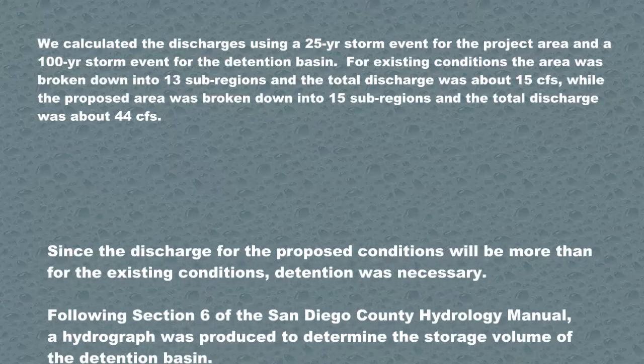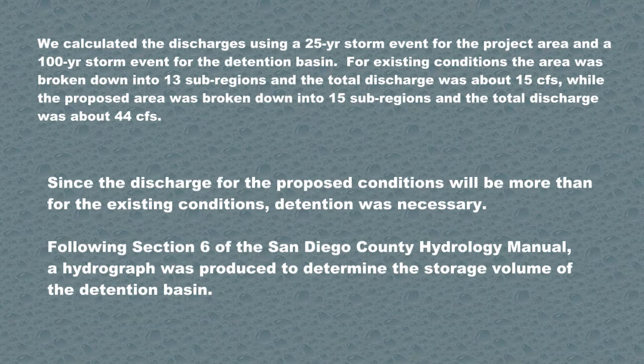Since the discharge for the proposed conditions will be more than for the existing conditions, detention was necessary. Following Section 6 of the San Diego County Hydrology Manual, a hydrograph was produced to determine the storage volume of the detention basin.